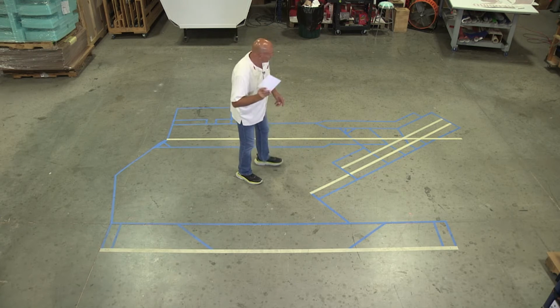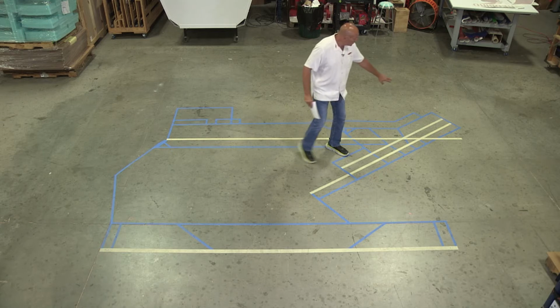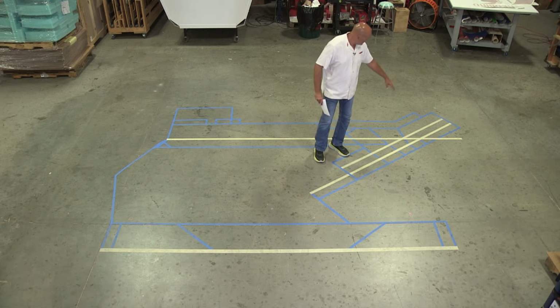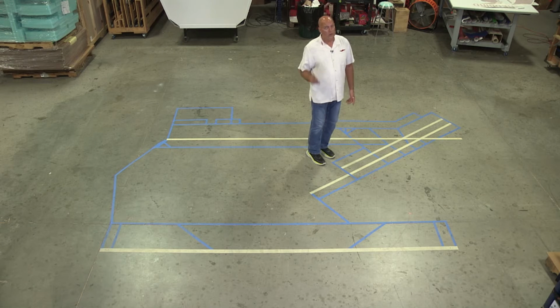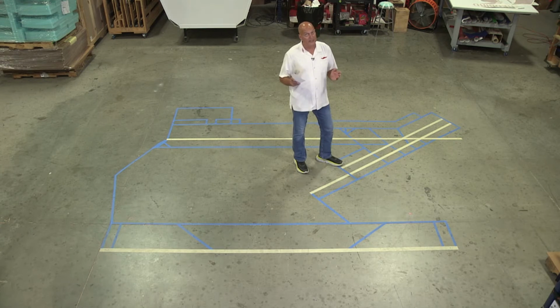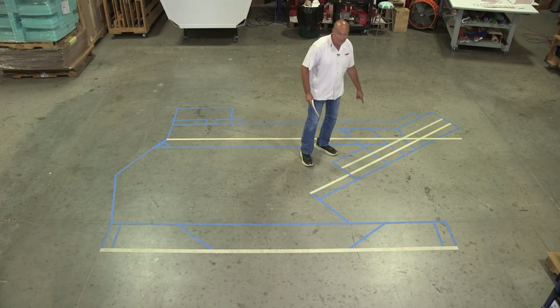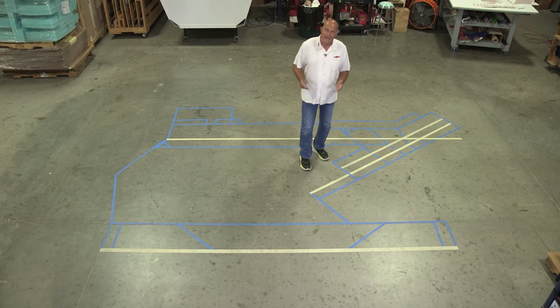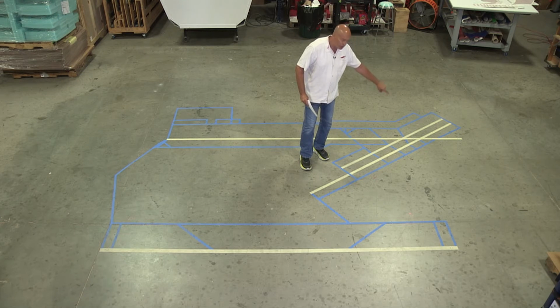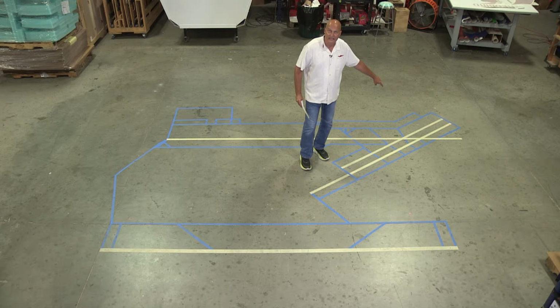Now, here's another thing to look at here. If we take a look here at where 2-6 right and where 2-2 left and 2-2 right converge, what could possibly happen here? Well, when you look at an airport diagram, would you expect to see some hot spots perhaps around this area here? Yep, I would think so. And I would ask my students why they think that some of these areas through here might be designated as hot spots. Why do you think that is?